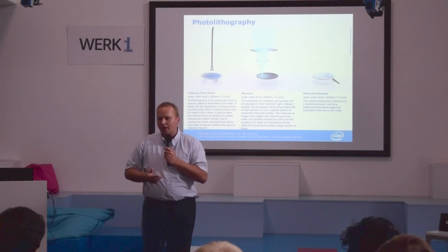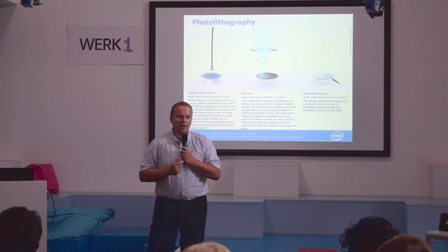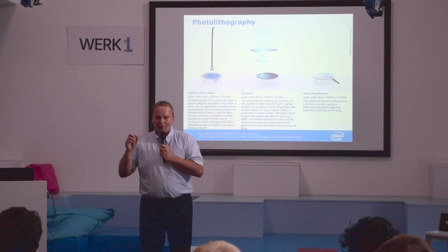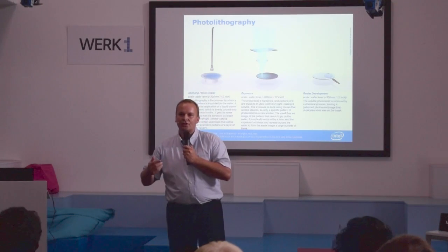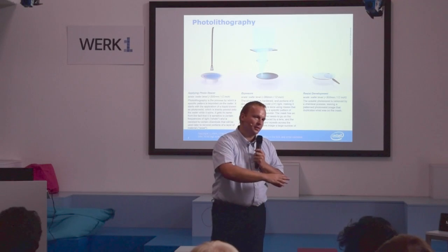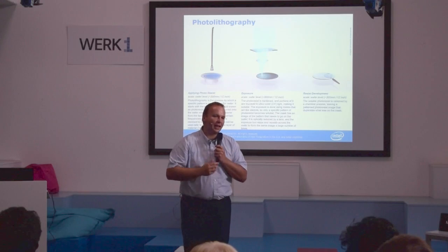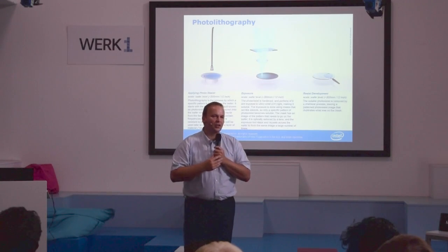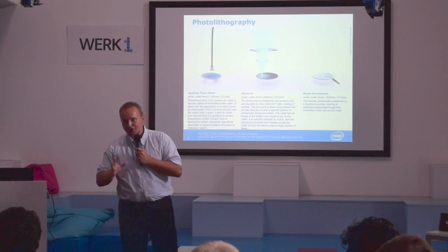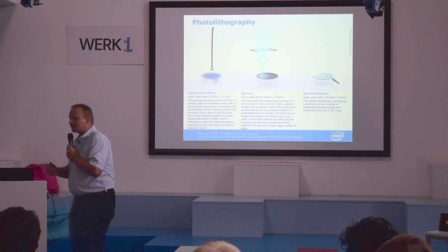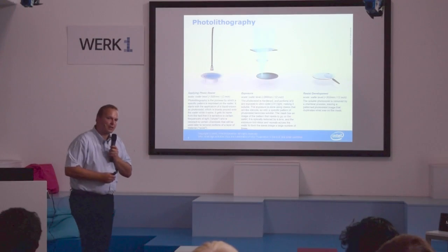And one of the most complicated things we do with regards to the lithography process: we have masks that have a certain determined depth, and we use the interference of the light waves that go through the mask in order to reduce the wavelength of the light behind the mask and create the structures that we really want to create. Okay? So this is one first important step to understand when we start the silicon manufacturing process.